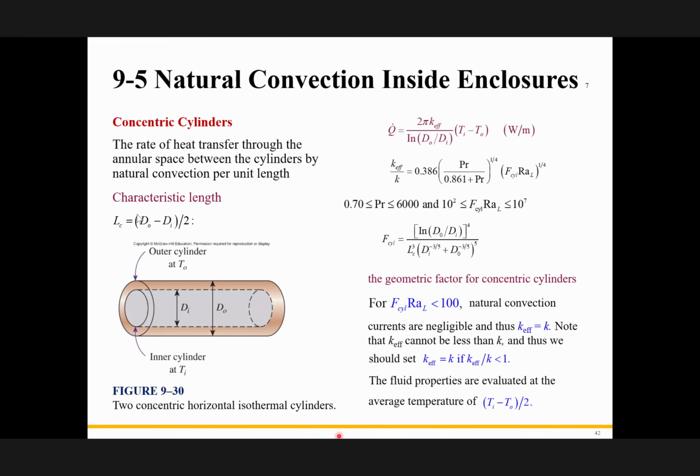Okay. Now, sometimes we have two pipes, one inside the other one, and this again happens in a solar collector. Inside the fluid passes through the tube, and outside there's a glass. This is one simple application, and you can have it in many other applications. If the solar radiation comes, hits this glass, this pipe is black, absorbs radiation, and heats up.